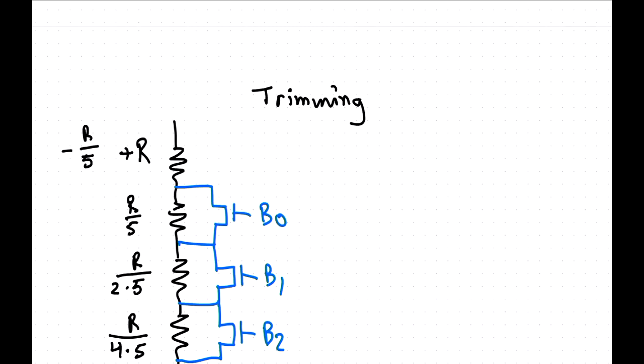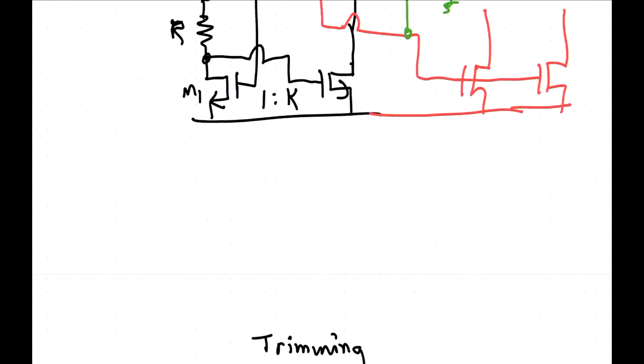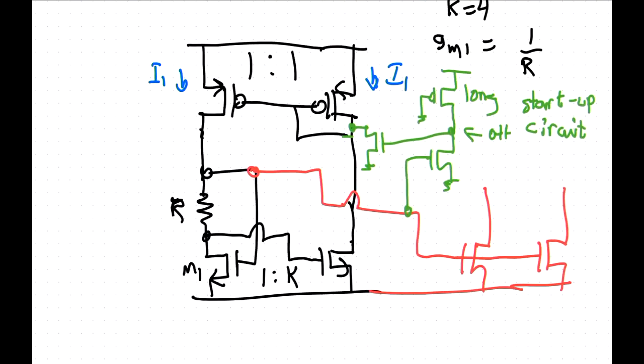Yes. So basically, we normally don't care about the transistor, we can just ignore it. Well, you want to design it. If you look at this circuit here, this is really just a biasing circuit. It uses static current, but there are no signals in here. So it's 0 Hertz, a DC value. So it doesn't really matter if you have capacitance sitting along that. The capacitance parasitic is not important, not in this circuit anyway.